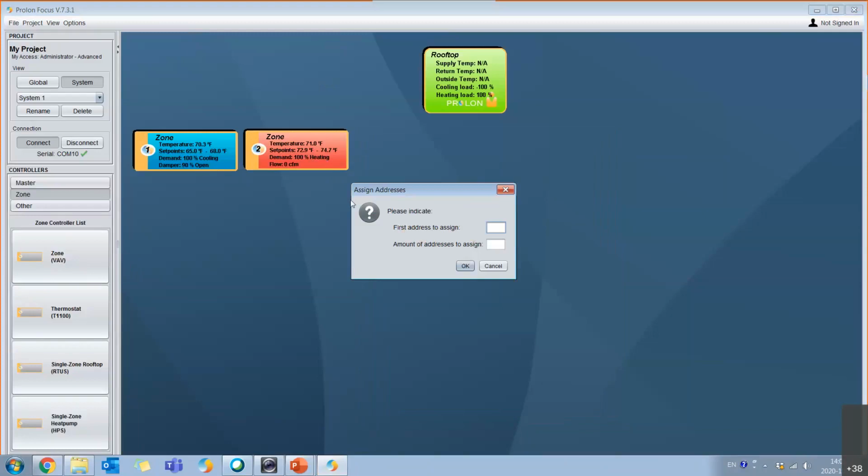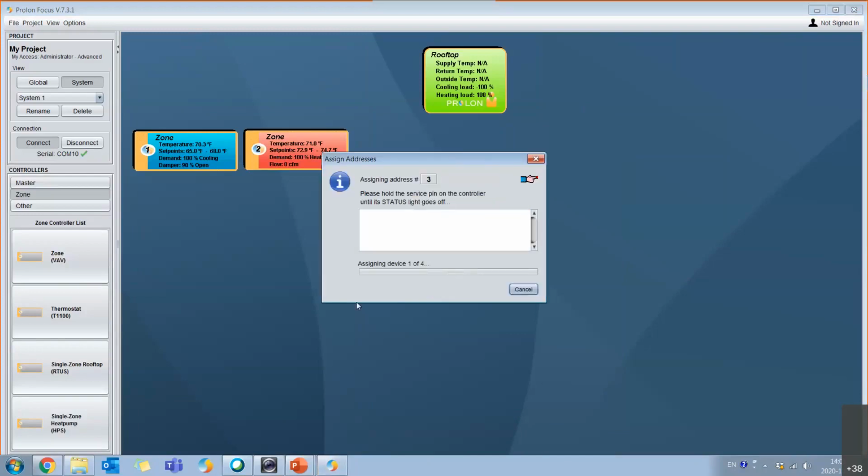So what's the first address I want to assign? Well, I know he's 1, he's 2, he's 20. So let's say I'll start with number 3, and let's say I've got another 4 controllers which I want to address. So now he's waiting for you to go press on the service pin on the controller.